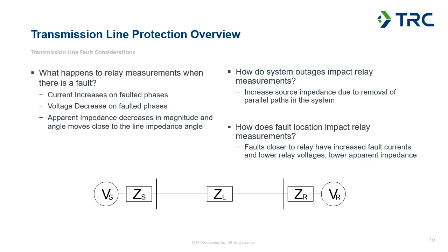So typically when we're running faults, especially if we're looking for a minimum quantity, we're going to find the lowest amount of fault current for a given scenario as part of our fault calculations. We're going to be evaluating with both all lines in and single outage considerations.